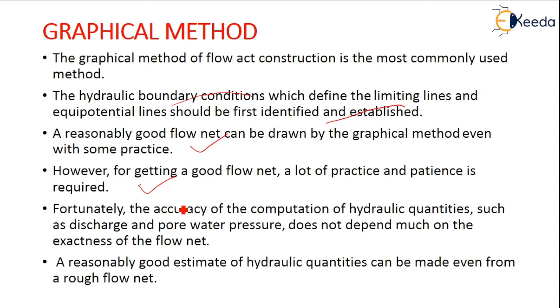Fortunately, the accuracy of the computation of hydraulic quantities such as the discharge and the pore water pressure will not depend much on the exactness of the flow net. So a reasonably good estimate of hydraulic quantities can be made even from a rough flow net.